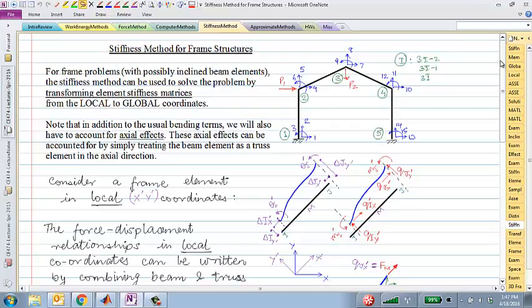And then finally, we started off the stiffness method for frames, where we said that essentially these are all elements that can bend. These are beams in their own local coordinate systems, but when assembled, this forms a frame structure where each node now has 3 degrees of freedom instead of 2 degrees of freedom. So for this structure, for example, we created 5 nodes, and for a general node i, if the degrees of freedom are 3i minus 2, 3i minus 1, and 3i, then for 5 nodes, we immediately have 15 degrees of freedom, right?